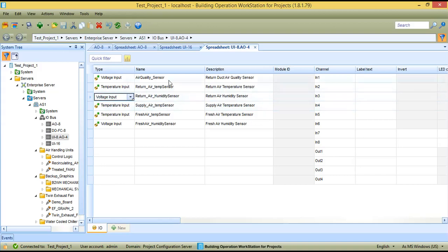Now in temperature, you have to check your temperature sensor and configure it correctly. If you are using a 10K type of temperature sensor, you have to specify the type of temperature sensor. I have shown you already this one in my previous tutorial.